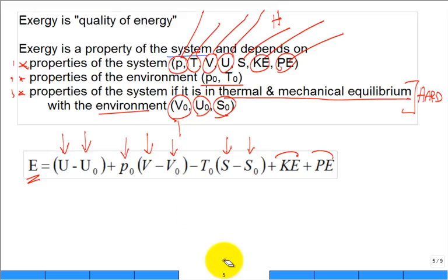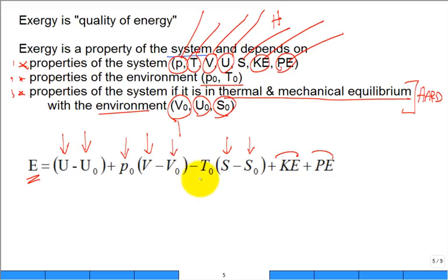All right. Let's talk about this. What about this temperature and this pressure? Somebody said, oh, it's 25 degrees C. Are you going to put 25 degrees C in there? Or are you going to put in 298 Kelvin? Or does it make a difference? First of all, does it make a difference? Yeah, it does, right? And from your experience in Thermo 1, what do you think? You better put it in absolute temperature.